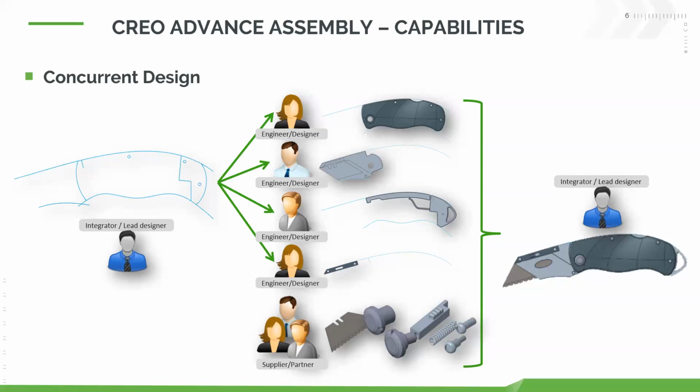And what's really great about this is at some point later on down the road, if you're doing a design review and that lead integrator or designer wants to make some changes here, they might want to make maybe 3 slots for the fingers instead of 2, or decrease the curvature. Well, whenever they do that, it's not going to break everything that was shared out from there, right? Whenever you go through and make those changes to that initial skeleton, all those other members that have built their designs based off of that are able to be flexible. They're able to update in accordance with that as well. So data sharing using copy and publish geometry is how we do those types of things from our skeleton models.